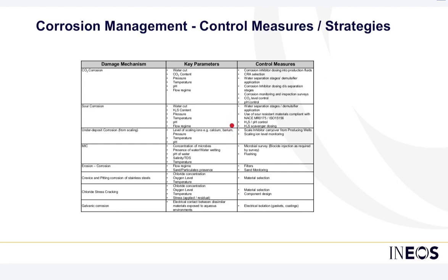And how do you do that? You start to apply the right corrosion inhibitor, make sure that it is always available on the surface of the material. Ensure that you have a material that is in good order, and you ensure that the surface is clean enough for the corrosion inhibitor to build the film on it. If you have an MIC problem, for example, you might then discover that you might have to do some flushing. So there are a number of ways to have all of this. For high temperature damage mechanisms, you will have to definitely rely on material selection, but understanding damage mechanisms is the key message here.